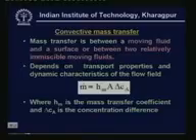And similar to Newton's law of cooling for convection, we can also write convective mass transfer as m dot is equal to Hm A into delta Ca, where Hm is the mass transfer coefficient, A is the mass transfer area, and delta Ca is the concentration difference.